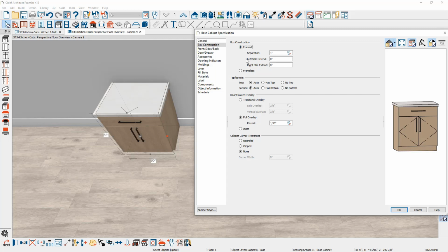If I come in here and put in an extended style of maybe 5 inches, you'll see in the preview diagram down here that the extended style automatically appears. Then you can list that in your cabinet nomenclature, and if you want to put it in your cabinet schedule, cut to fit, or whatever appropriate information is, you can do that.